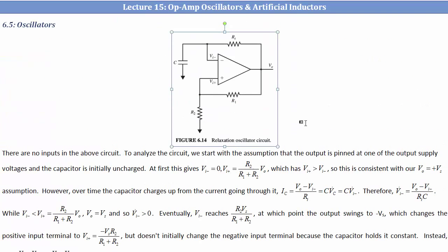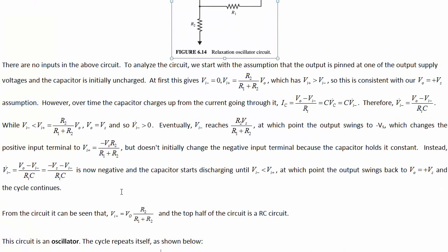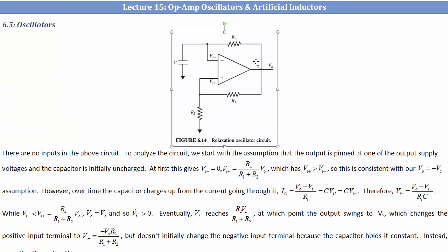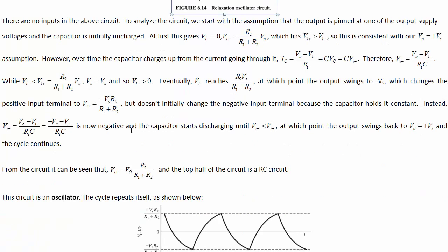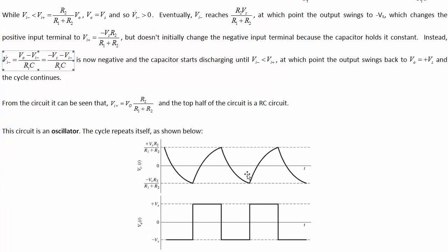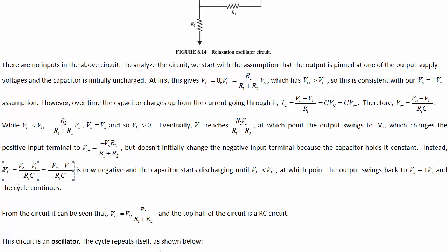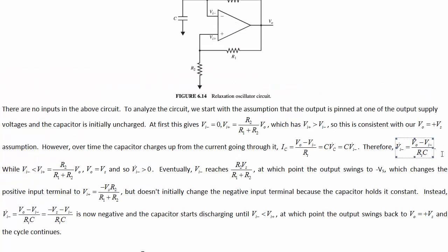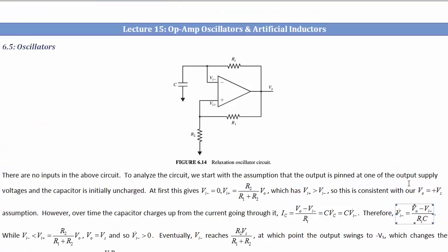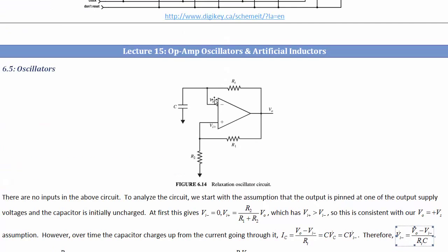We explained it qualitatively. Feel free to look over the notes and run the math of this. It's nothing you haven't seen before to calculate what the circuit is actually doing numerically. The critical component that you'll come up with is the left part of this equation here. This tells you the rate of change of the voltage at the negative terminal in terms of the output voltage at that moment and the voltage at the negative input terminal.